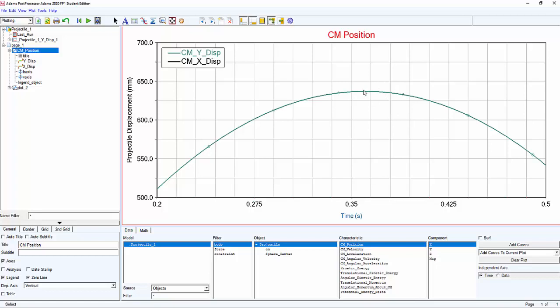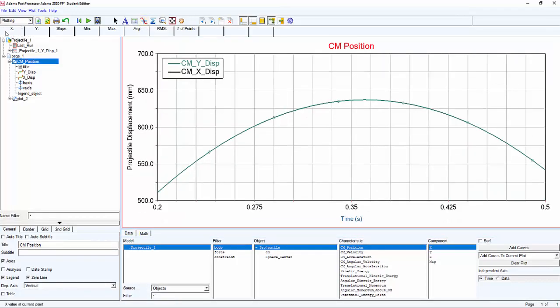Now, what is this value? How much is this value exactly? Oh, you can read it from here, but I wanted to have it exactly. So you can use this tool, which we use for plot tracking. If you click on this tool, it will give you statistics about this curve. This tool is going to show this crosshair. See this hair? This hair is moving over every step from your simulation. So you can move your cursor to the left or to the right.